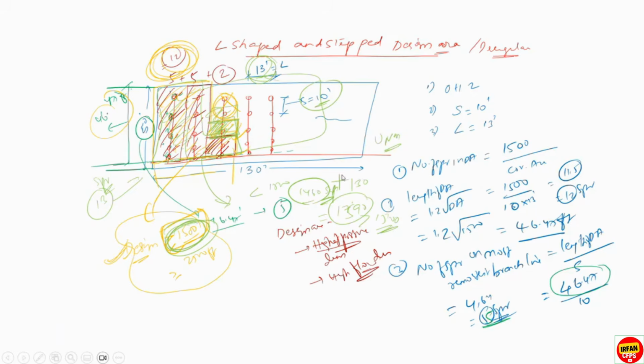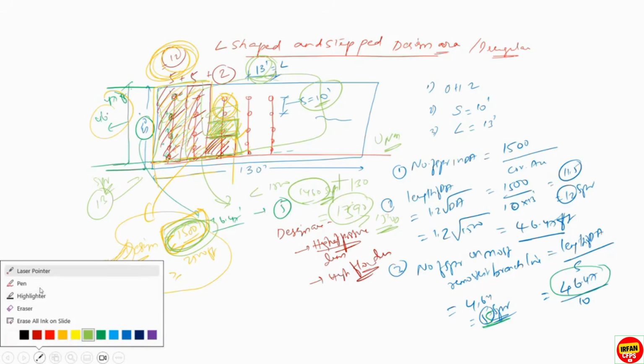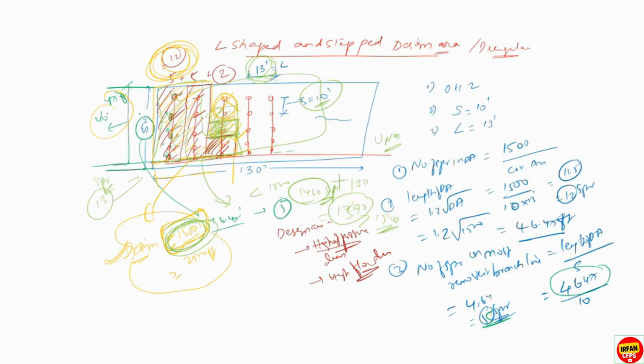Okay. Now, since you have the cross main near the wall, you got an L shape, right? But if your cross main is in between, I mean, if from the cross main your sprinklers are connected on one side and the other side as well, on two sides, then how do you select the design area? So just a moment, I'll try to draw again.